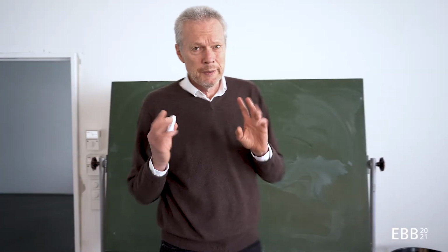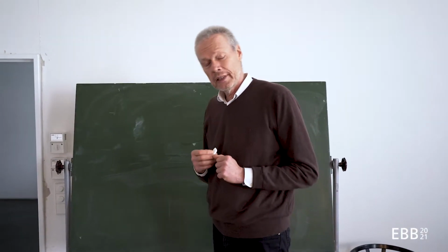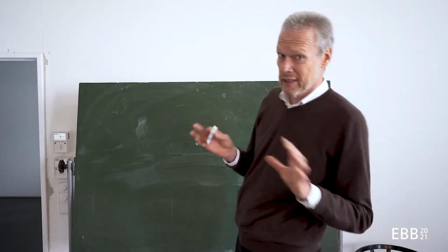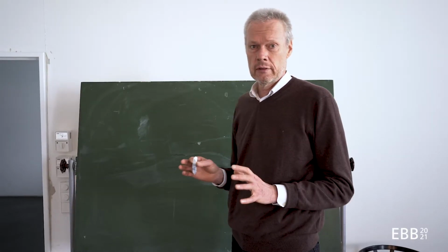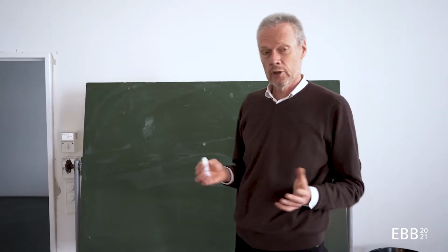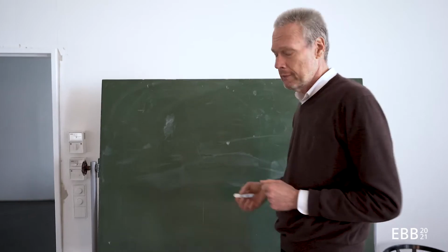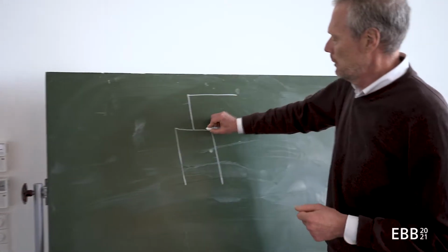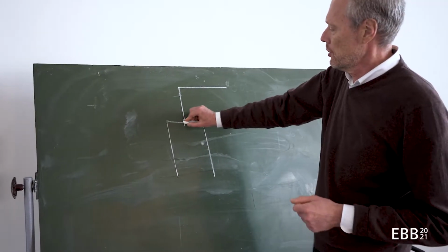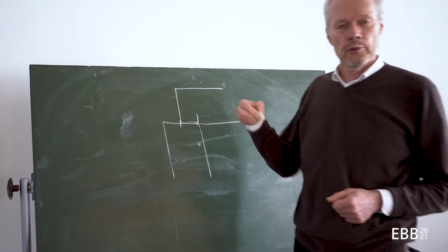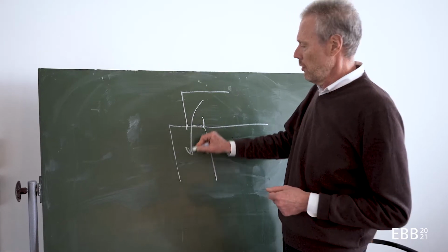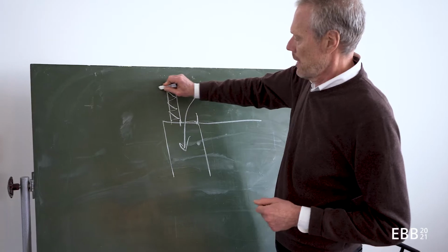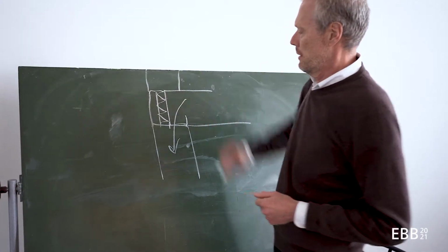So we have two big phenomena here that we have to take care of. One is gravity, and the second is how to keep things in place, a fixation. So if I have, for example, a concrete floor slab, it will hold on the wall by itself. It takes a certain surface to transmit the load in the wall, and then I have to keep a little distance here, to be able to insulate it.